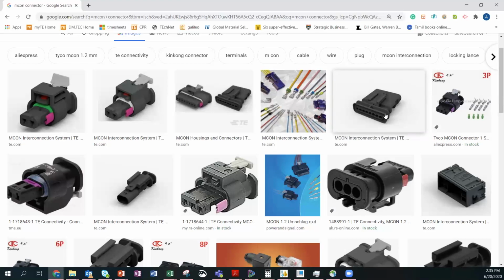And temperature, even at 150 degrees Celsius. Water boils at 100 degrees Celsius, and this has to perform even at 150. Small things can cause a big failure. If a part, which is all plastic polymers, emits some gas at higher temperature, it gets rust and will break down. So I should make sure nothing of that sort happens.